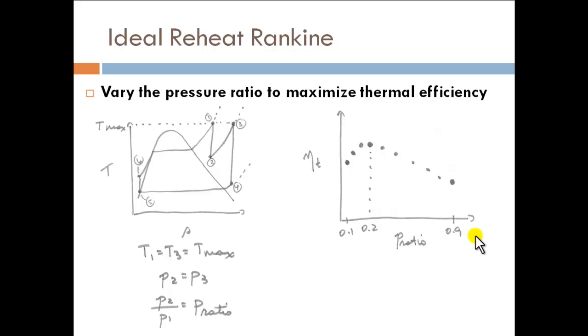And as designers, what did we think we should do after that? Well, we have a pressure ratio range within which we can operate, so we decided maybe we go to 0.1, maybe 0.9, and use our function 2 more times, just to increase our understanding, our knowledge of what's known as the design space. And remember, this is still at a constant T1 and T3.